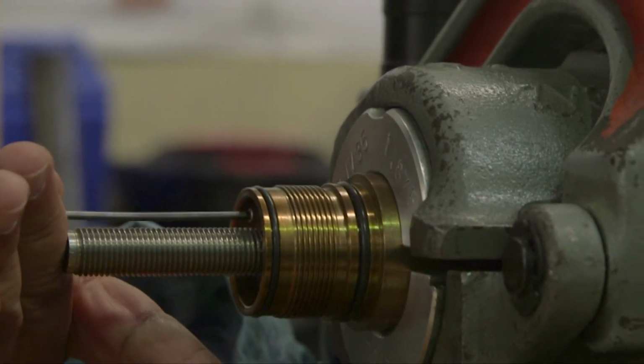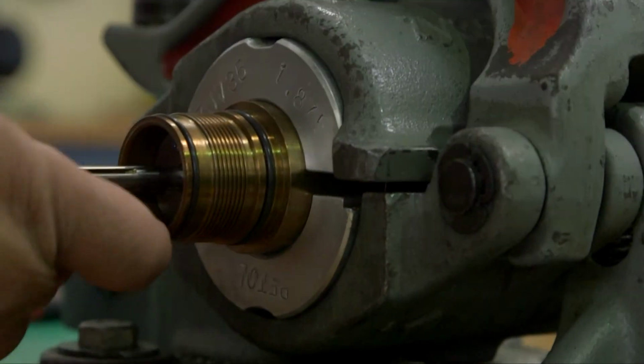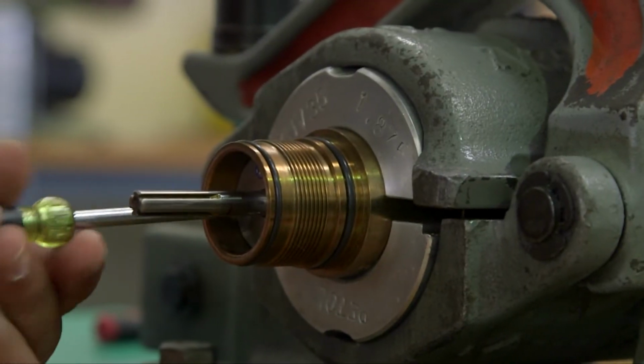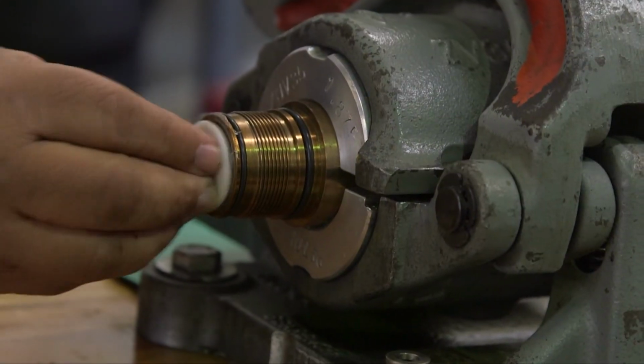At this stage, the piston assembly tool is removed and the valve components can be assembled onto the drivetrain of the pulsar. Additional grease is added in front of our piston compensation system to exclude contaminants and debris from the seals for as long as possible.